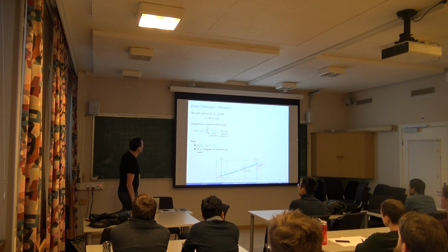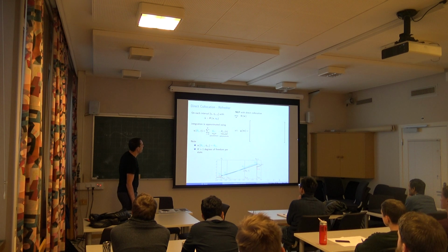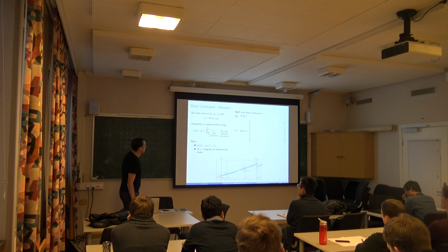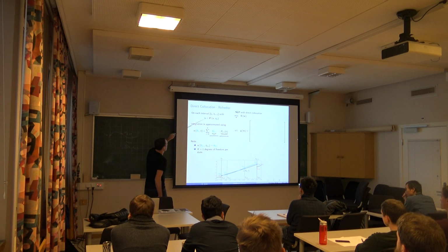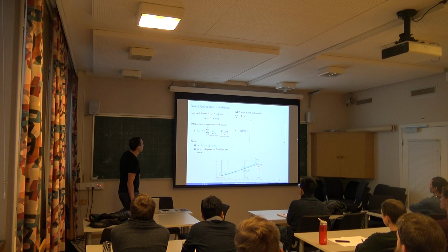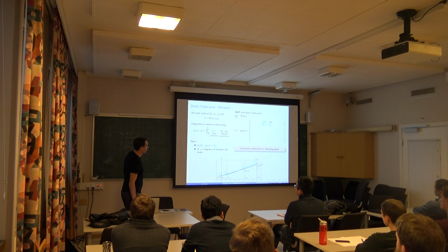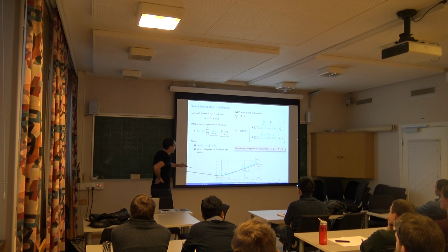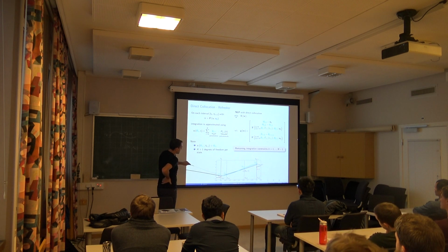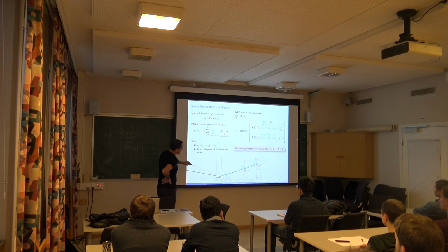So we have this setup, and the way you would write down your NLP, in this case, you have a simple ODE. You have your initial conditions, then that's a shooting gap, and then you have the direct collocation constraints that will basically support the integration inside the NLP, and then you repeat that. So on every shooting interval, this must match the xk, and the xk itself also matches essentially the end of the previous interval.